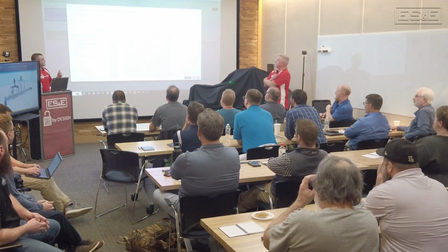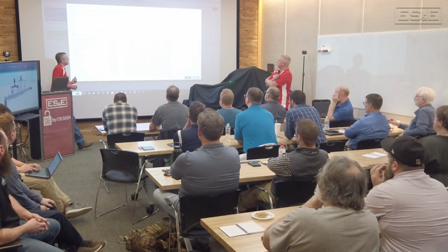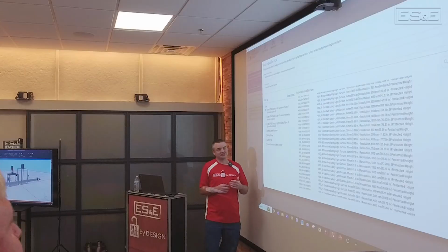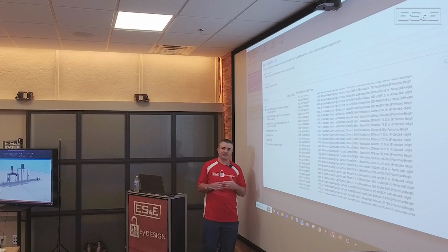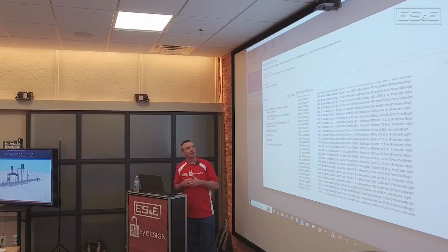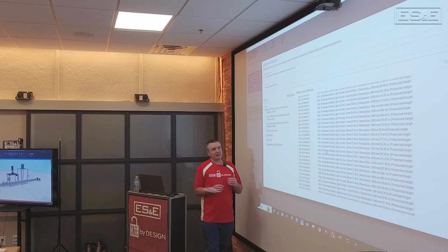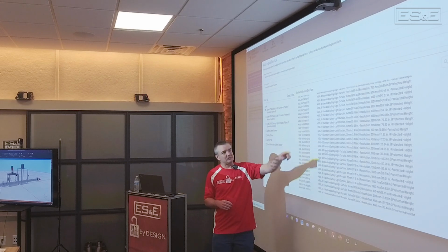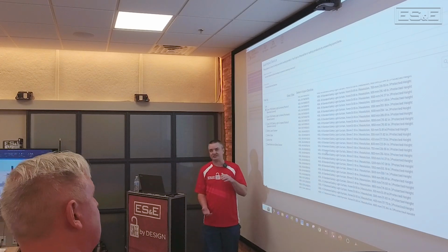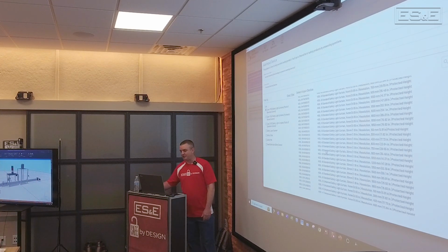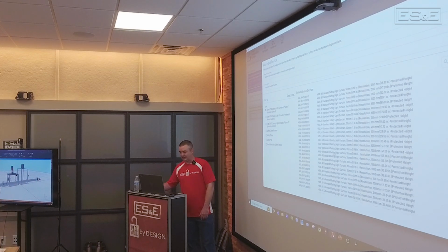So, Kevin, that looks like a lot of part numbers. Help me out here. How am I supposed to know which one is which? So this is just a list of all the Rockwell light curtains, the 450L series, because that's what we want to use, the newest safety light curtain for your solution. And the difference between these is not as bad as it looks. Basically, they're designated in our 14 millimeter resolution offerings and our 30 millimeter resolution offerings, and then the length of the curtain itself, so a protected height. For your machine, I think we can get by with the smallest one and a 30 millimeter resolution option.